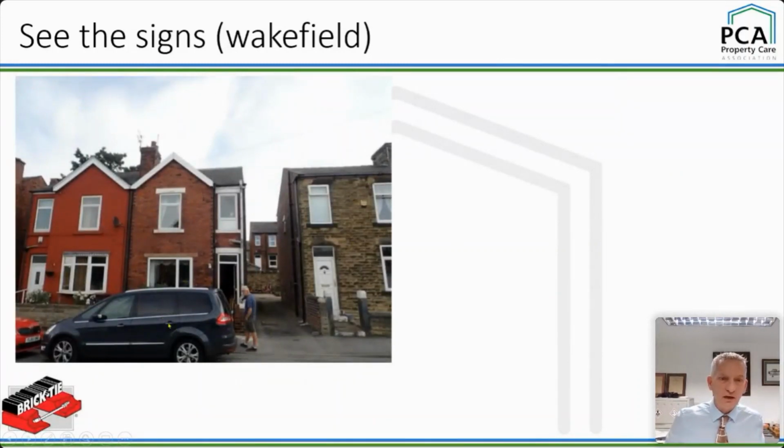So for surveyors again, I like this little example. It's the middle house we're looking at, okay? Gable, another gable. Two gables close together. That increases wind loading, and it's also the alternating nature of it, because when wind, I used to fly paragliders, and you always avoid going behind the ridge of a hill, because when you go behind the ridge, you can get into a rotor, and your paraglider turns into a bag of washing, right? And that's because when wind is put under pressure, as soon as that pressure is released, it goes mad, right? Wind is blowing through the gap, that's sucking both walls together, but as it escapes, it goes into rotor, and you get this vibration pulling the house.